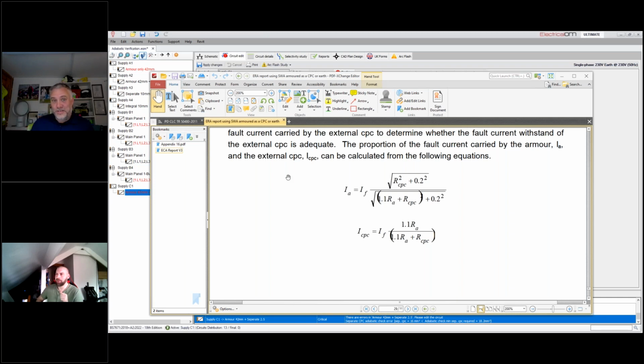If we put it into a duct and the duct meets the requirements of BS EN 61386-24, which is a 750 Newton duct, 750 N duct. So it's what we call probably twin wall ducting, rigid duct or something. More commonly known as twin wall, is the usual site term people use. If you put a twin wall duct in the ground, it's providing equal or adequate mechanical protection as what the armor should be, so you can omit then the armor in those cases.